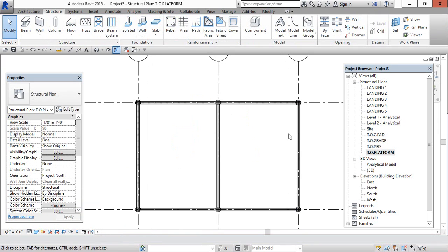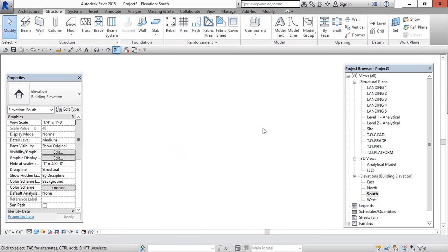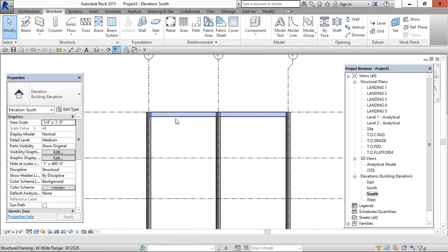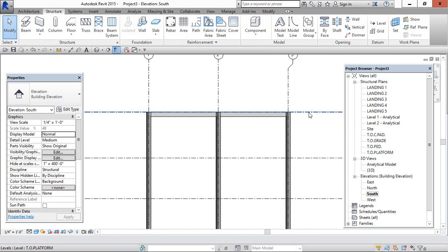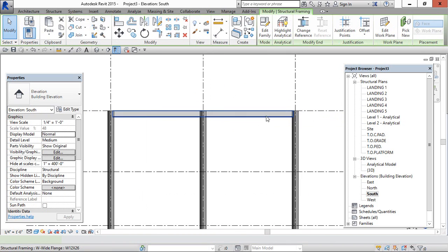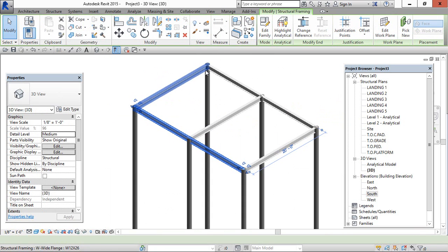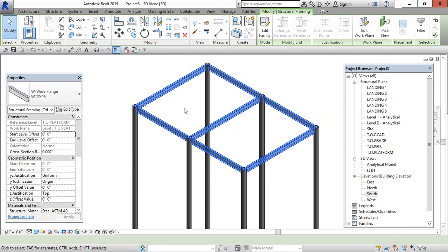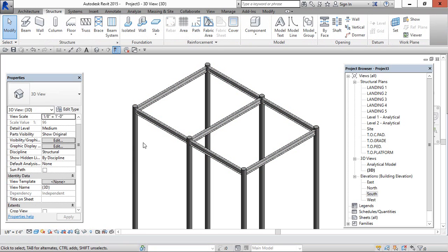Now we have created this one. Go to elevation. We need 6 inches here, top of concrete. This concrete will come above this, and it will be in this level. So select all, go to 3D. Yes, A for select all, and you can find an option here, set value here minus 6 inches. So now it has come down.